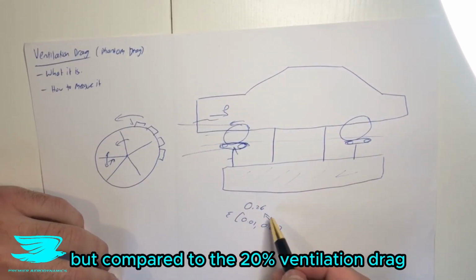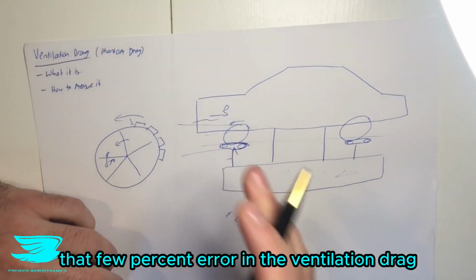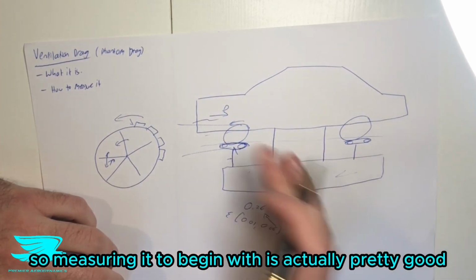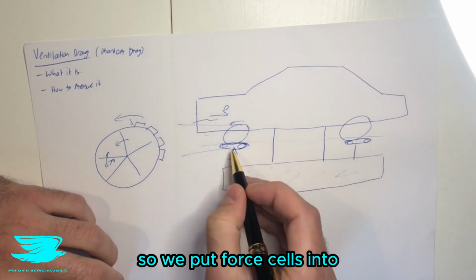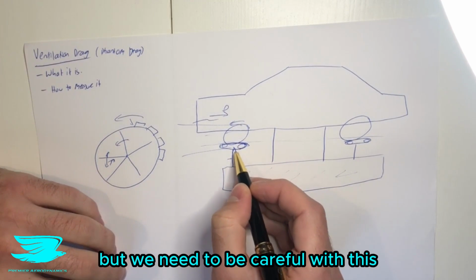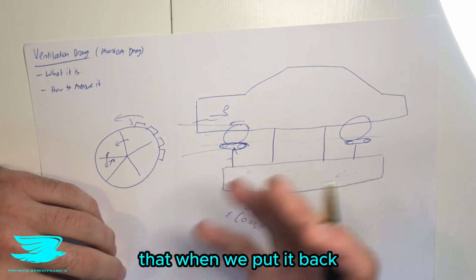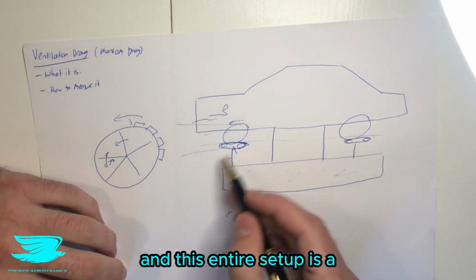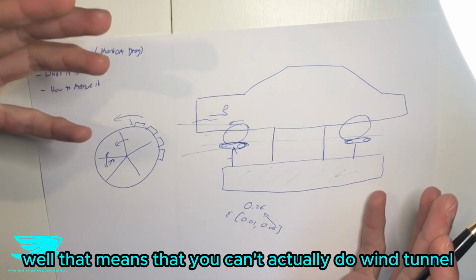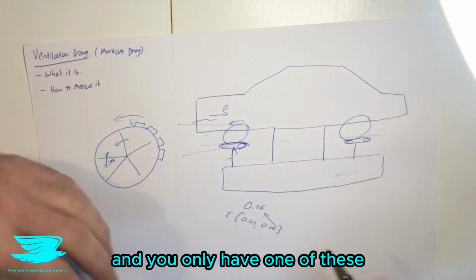But compared to the 20% that the ventilation drag increases the car's drag by, that few percent in the ventilation drag is not that much of a problem, at least these days, because no one's actually measuring this anyway, so measuring it to begin with is actually pretty good. So we put force cells into these wheel drive units, and that's pretty good. But we need to be careful with this, because if we do change the wheel drive units, there's no guarantee that when we put it back, it's actually going to be the exact same way. And this entire setup is a multi-million-dollar setup, so we want to make sure that we get it right. And if we do break it somehow, well, that means that you can't actually do wind tunnel measurements until you get this fixed, and you only have one of these.